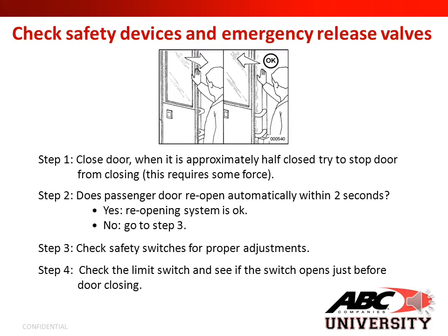Step 2. Does the passenger door reopen automatically within 10 seconds? If yes, reopening system is okay. If it did not, we would go to Step 3 in the maintenance manual. Step 3 would be check safety switches for proper adjustment. Step 4. Check the limit switch and see if the switch opens just before door closing.